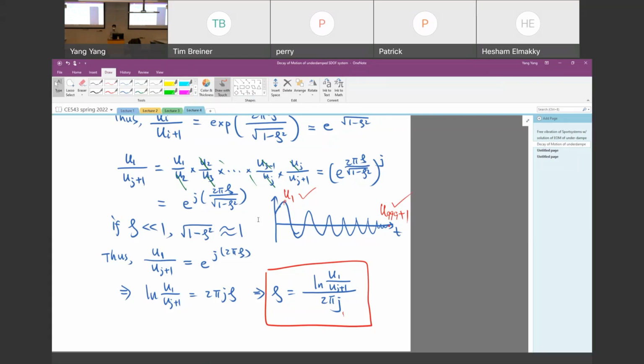Dynamic testing is pretty easy. You just excite the structure in a lot of ways. For example, you can use a very heavy hammer to hit one side of the structure frame to make the structure vibrate, so that you can measure the displacement or acceleration of the frame. As long as we have that information, we should be able to get damping information there.